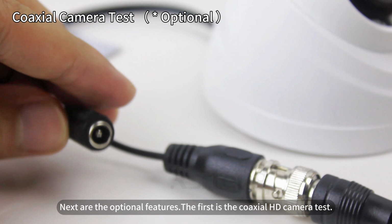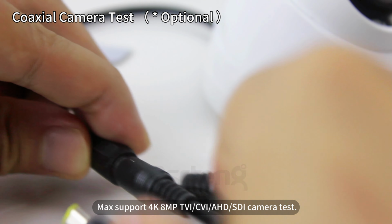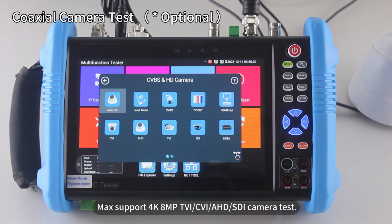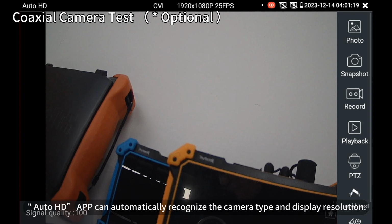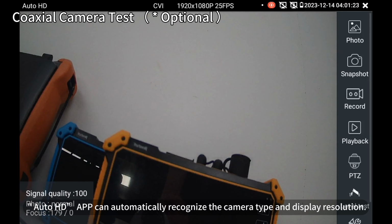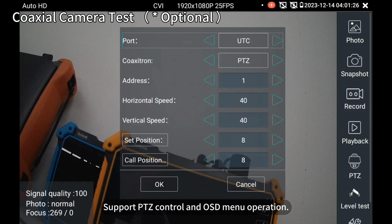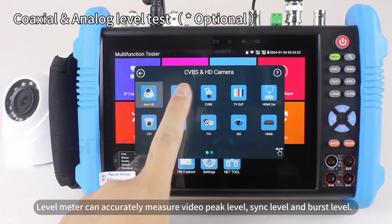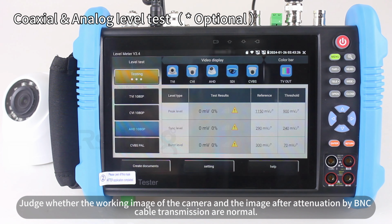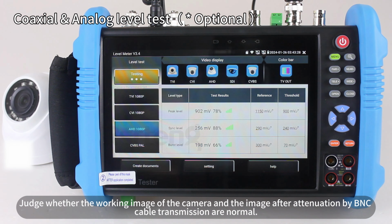The first is the coaxial HD camera test. Max support 4K, 8MP, TVI, CVI, AHD, CDI camera tests. Auto HD app can automatically recognize the camera type and display the resolution. Supports PTZ control and OSD menu operations. The level meter can accurately measure video peak level, sync level, and burst level, to judge whether the working image of the camera and the image attenuation by BNC cable transmission are normal.